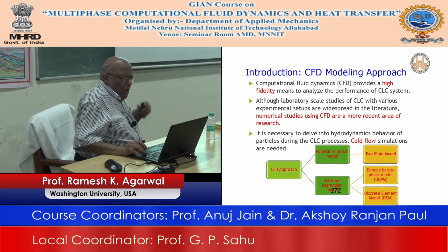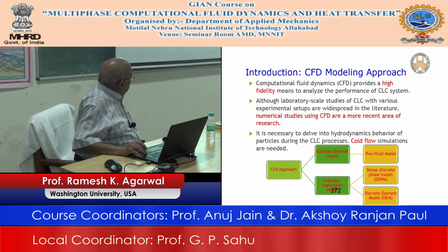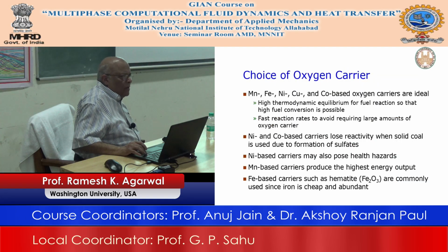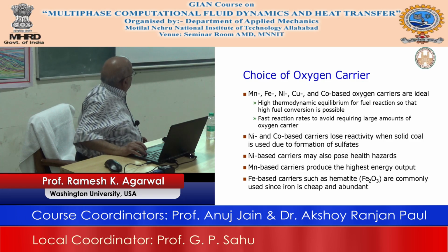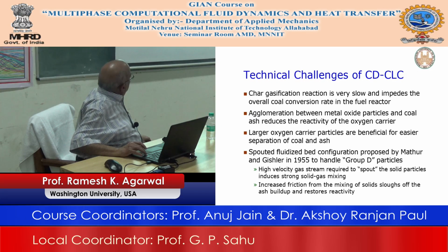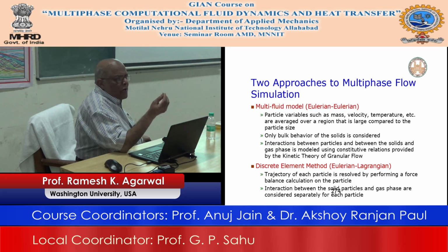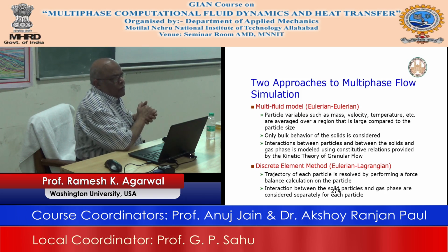Now the choice of oxygen carrier, I will not go into it because it's needed, as I said, to have pure oxygen combustion without the presence of nitrogen. And then, as I have mentioned to you, you want to make sure that you have all the coal burnt, and so there are a lot of issues there. There are issues also, if you want to go into sophistication, about what should be the size of the coal particle to obtain good combustion. All these things people have worked out in the last 20, 30 years, and they know what to use.